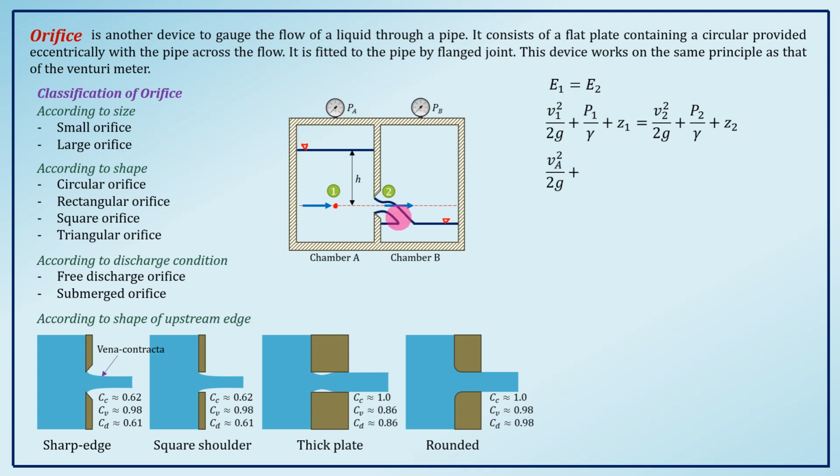It is the summation of the air pressure, plus the pressure due to the liquid, which is the unit weight times this height h. So we have PA over gamma plus h. This contributes our air pressure. Then our Z1, since point 1 is on the datum, is 0.